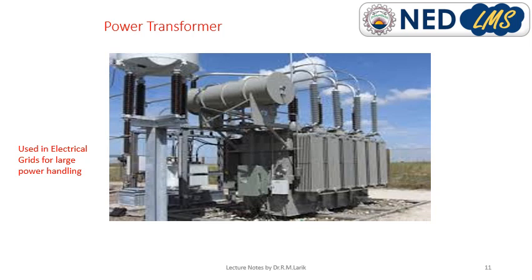Power transformers are involved at two places, one at the generation phase and one at the grids. Means one for transmission purposes, one for distribution purposes. The network converts from 11 kV to 132 or 230 kV, and again that 132 and 230 kV is converted to 11 kV. In both places we use power transformers because of large power handling. After 11 kV we use distribution transformers.